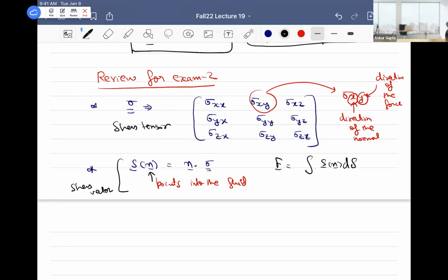As you can see, I hope, in this entire part, force calculation is one of the key components that differentiates this part from part 1, because at the end we always try to calculate drag, force, and torque, which you're doing in problem 3. And whenever you're integrating, please make sure that you're always decomposing in Cartesian coordinates, Ex, Ey, Ez. You cannot integrate forces in E theta, Er, or E phi, because the vectors are changing, and that's why you go to a static coordinate system where the vectors are constant, so that you can sum the values in each direction.